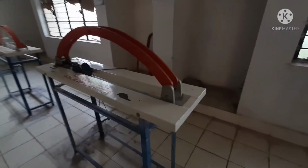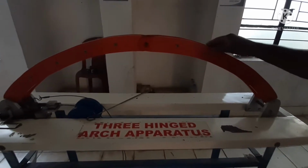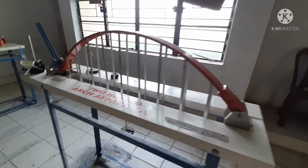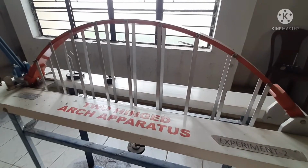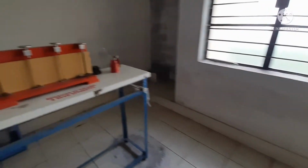Another apparatus we have is the three hinged arch. You can see the three hinged arch, and in this experiment we will find out the value of horizontal thrust and displacement. Another we have is the two hinged arch apparatus. In this experiment we also find the horizontal thrust and the displacement caused after applying the load.